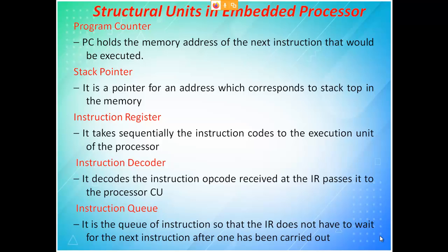Now the thing which you have to remember is what value the program counter will have when this particular line is being executed. Once this call is seen by the processor, your program counter will tell about 6001, because this call is written on line number 6000. So obviously 6001 will be in the program counter.